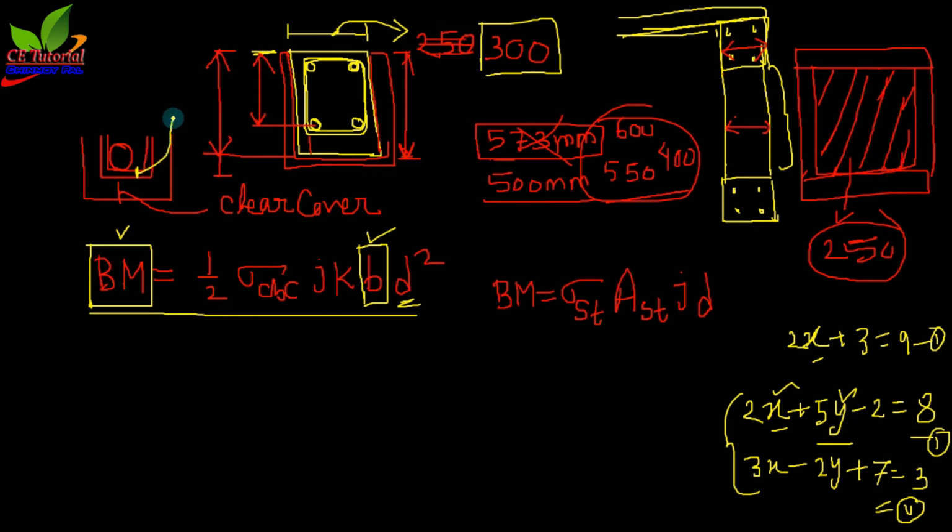Okay, so dia of stirrup, and we have to measure the effective depth from the center of the tension reinforcement. Please keep in mind, center of the tension reinforcement.